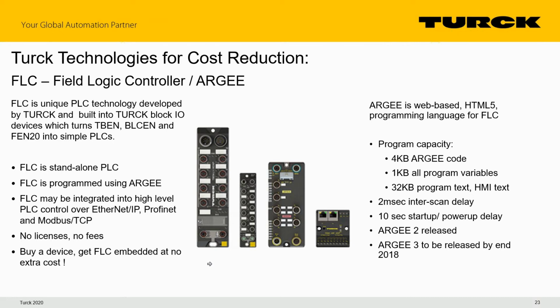So we could be passing through remote commands from a PLC until we lose communication. Then the RG program can take over and say, stop the pumps, wait 30 seconds, close the valves. So we are now working in a very staged and controlled method of shutdown rather than causing any water hammer or anything like that. The programming environment is simply using an HTML5 web browser. Right now, Chrome is our recommended web browser for this. And we can get scan times as low as 2 milliseconds.